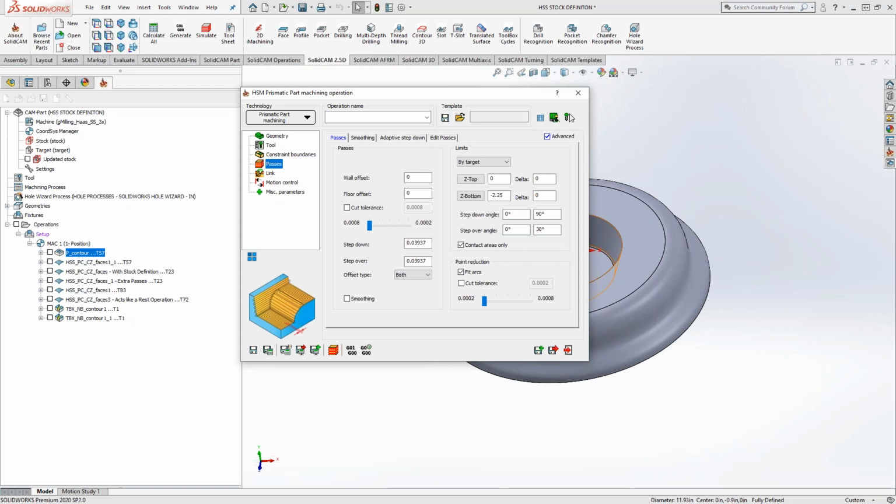What I mean by the pretty finish is you get those nice contour lines going in there. With iMachining, you can set your finishing, but you get a lot of the swirl marks. It's just visual. It still feels fine and everything, but you will see those swirl marks inside there. So those are my 3 favorite ones that I use on a consistent basis.